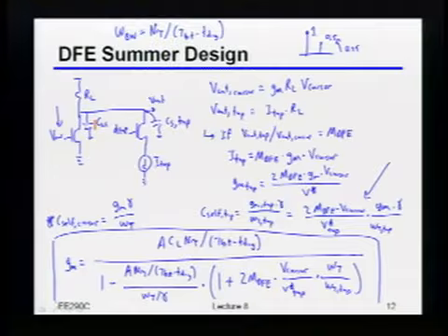And so notice the same thing sort of happens with the DFE because the amount of current you have to use in that DFE is also proportional to the GM you had on the input device in the first place, right? In other words, what the DFE is really doing to you is it looks a lot like just a differential amplifier or a standard common source amplifier, except that now the actual intrinsic bandwidth you can get is degraded by the amount of correction that you have to do, right?